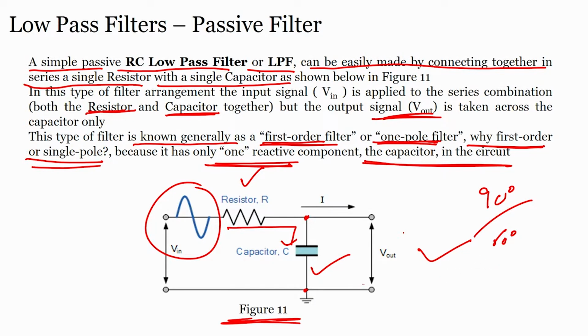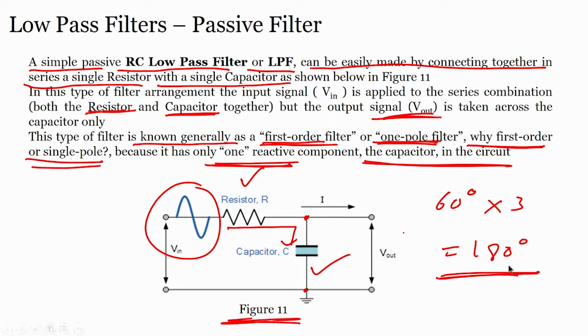In oscillators, how many RC were there? 3R and 3C or 3R and C, right, and then each one gave us how much degree of phase shift? Each one gave us 60 degree of phase shift. So, we had 3 RC, that means we got 180 degree of phase shift as a feedback to the oscillator, the feedback circuit to the oscillator.